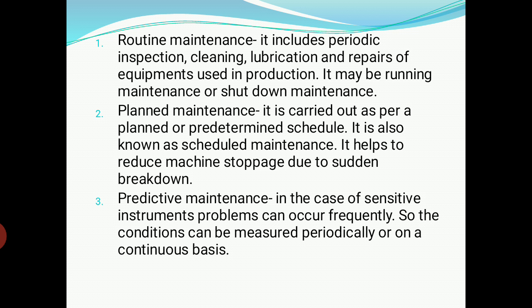and it helps to reduce the machine stoppage due to sudden breakdowns. Once you are taking up planned maintenance, you know that this type of equipment needs wear and tear checks at this point of time, or after these many hours of work. It needs checking whether it is in good working condition, or whether any worn out part is to be removed. So if you know beforehand, then we can plan accordingly, a schedule is prepared, and accordingly the maintenance of the machines is taken up.